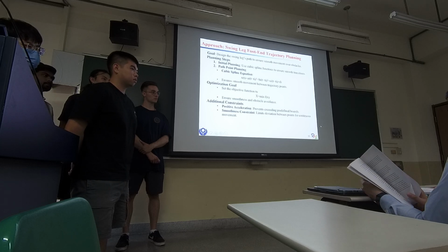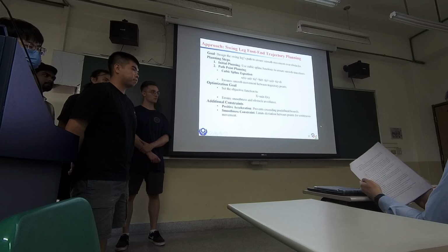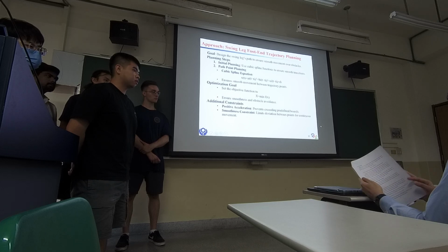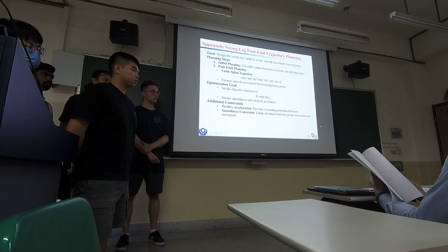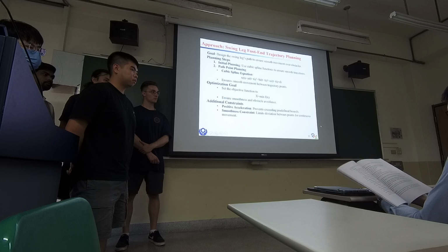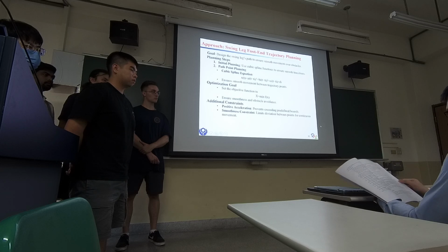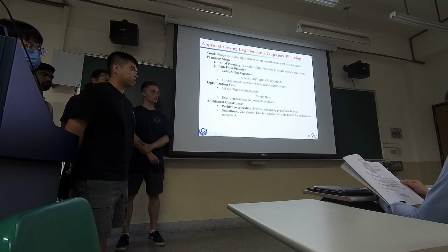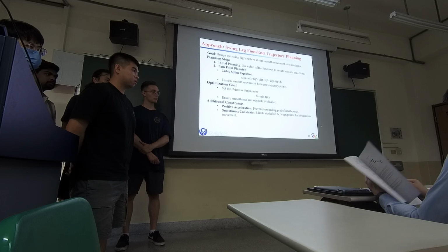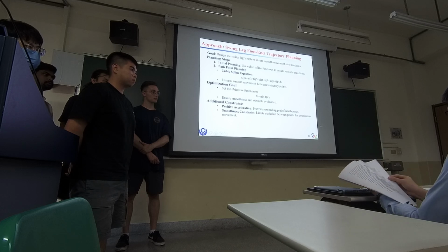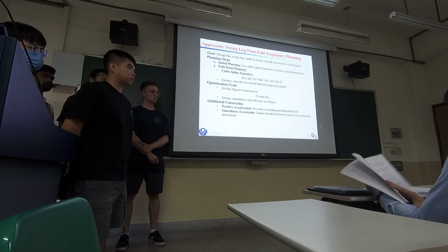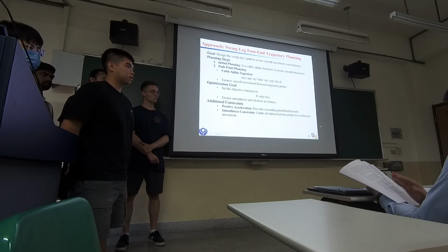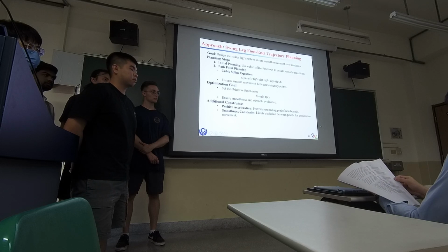You only rely on clockwise and counterclockwise rotation of some of the wheels on the left and right, so some other wheels may be slipping on the floor, right? You are not using mecanum wheels, right? You are using regular wheels. So there will be issues.